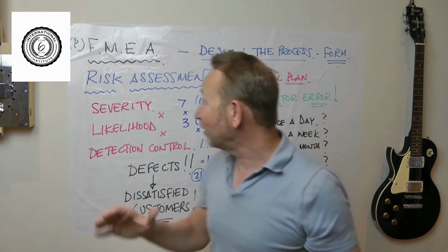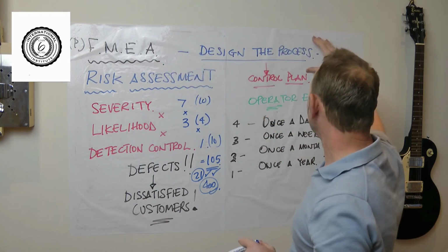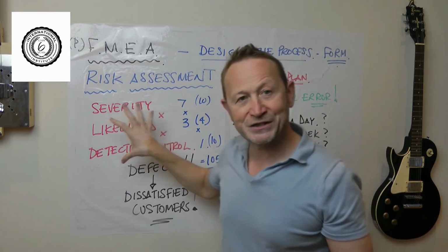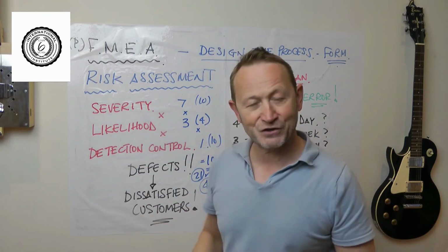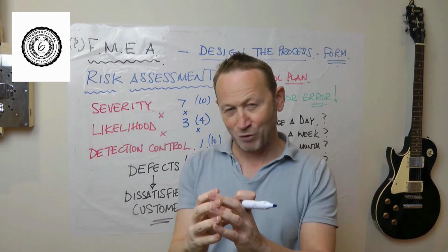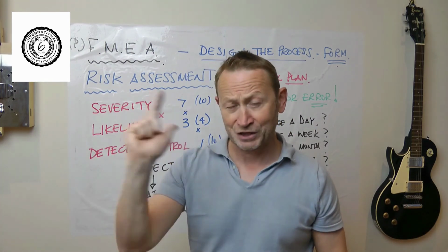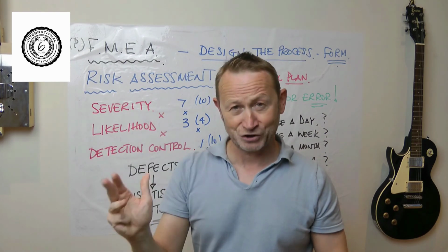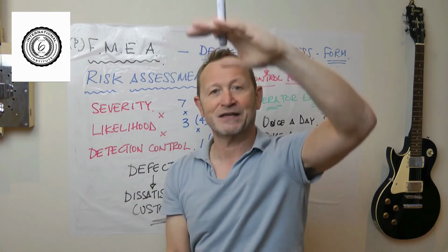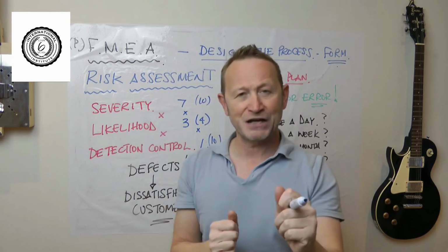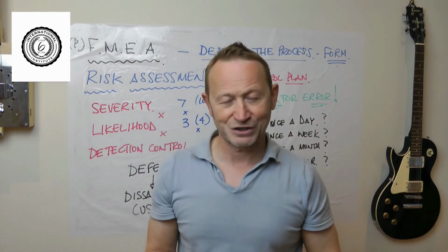So what I've done now, I've told everybody in my FMEA what my process looks like, what my potential risks are in terms of making defects and upsetting the customer. So I've told them how important each variable is in my process: times, temperatures, speeds, injection pressures. All of those numbers will all be in my FMEA, and I will say if they get violated, this is how important they are, and here is how I intend to control them.